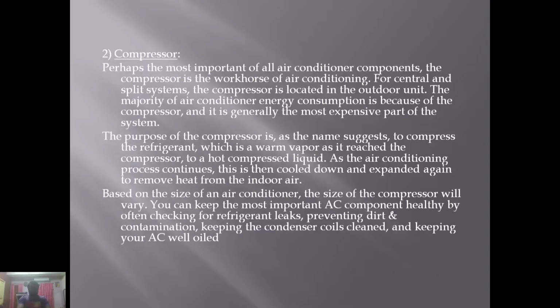You can keep the most important AC component healthy by often checking for refrigerant leaks, preventing dirt and dust and contamination, keeping the condenser coils cleaned, and keeping your AC well oiled.